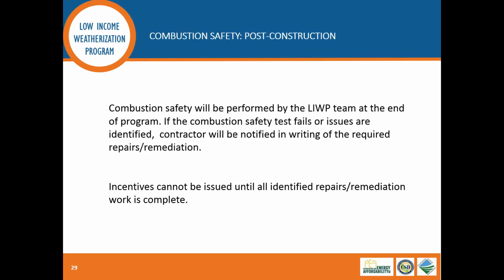Next slide, please. Combustion safety. So for those of you who are familiar with combustion safety, essentially what we need to do is verify that the project hasn't done anything that would cause a gas appliance to operate unsafely. That's primarily atmospheric appliances, so wall furnaces, or maybe a ducted furnace that's still an older atmospherically vented appliance, as well as in-unit water heaters.